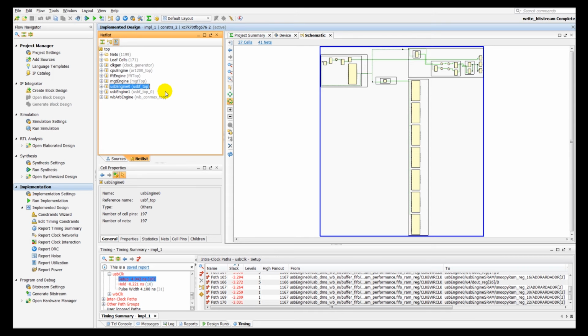By isolating clocks and critical logic, module functions really pay off greatly if you're going to attempt to floor plan the design. Floor planning logic modules that have a high number of interface signals or that are connected to buses that may travel all over the design are sometimes very difficult to floor plan. So now that we've determined that all of our troublesome logic is inside the USB 0, it makes it a good candidate for floor planning.